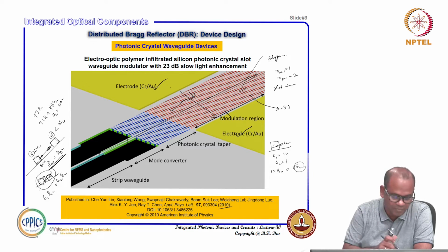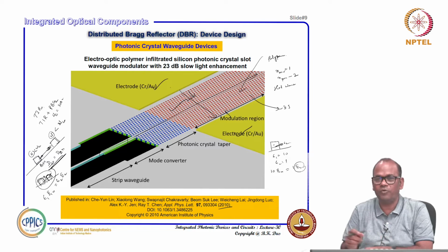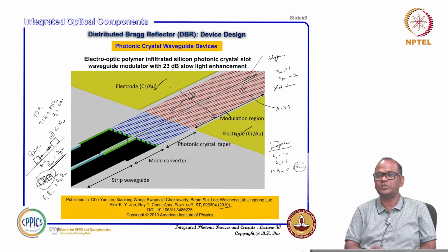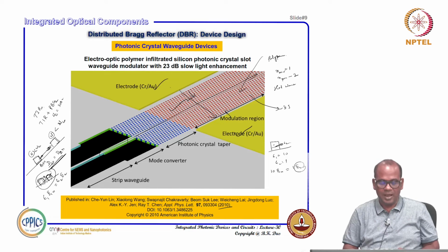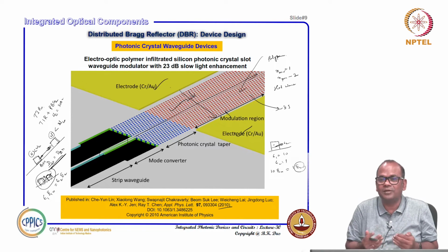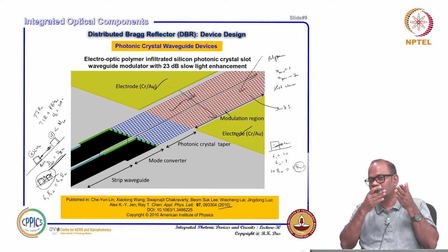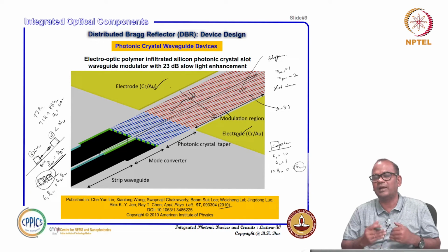But in this case, individually these ribs cannot support a mode, but when you bring them closer and closer, in the gap region, to satisfy the boundary condition, the field strength is enhanced and you can get mode-like solutions. If you solve Maxwell's equations, you will see that some eigenmodes and eigenvalue propagation constants exist, and as a mode it can guide.